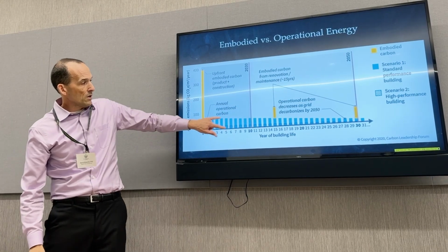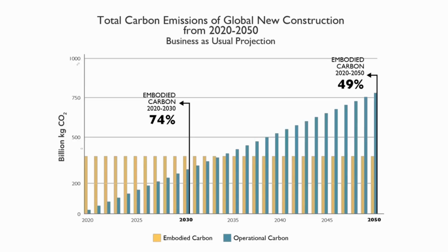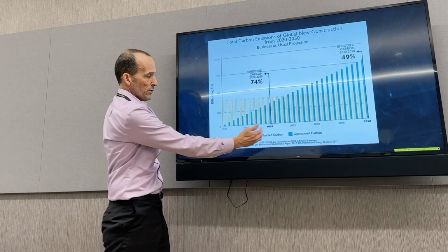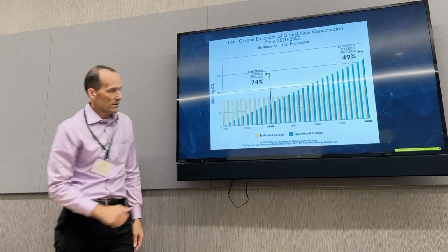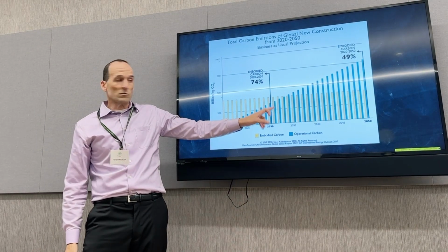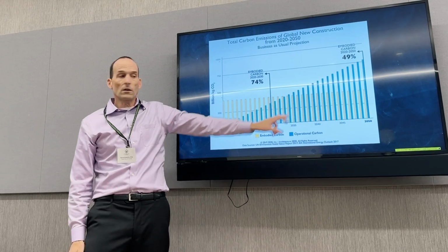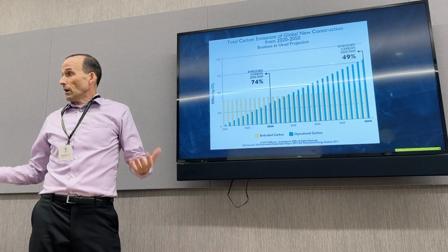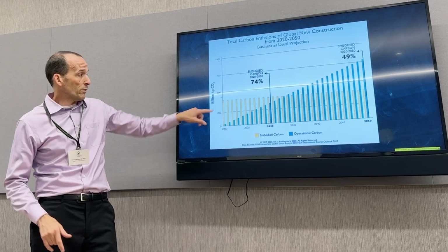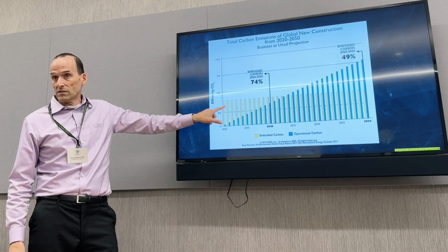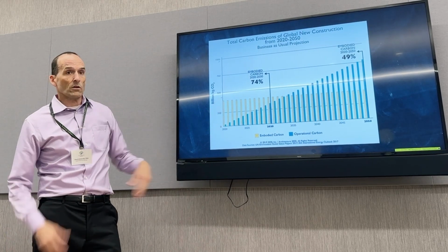Pretty soon, next slide. All these add up, and what we see is that embodied carbon is building here. Operational carbon continues to stack up and stack up and stack up. So on this building, 10 years after its manufacture, the embodied carbon was more. Like 14 years, now operational carbon becomes more, right? So now we know that operational carbon is impactful, but it's embodied carbon that has this huge impact, right? So how do we think about that?